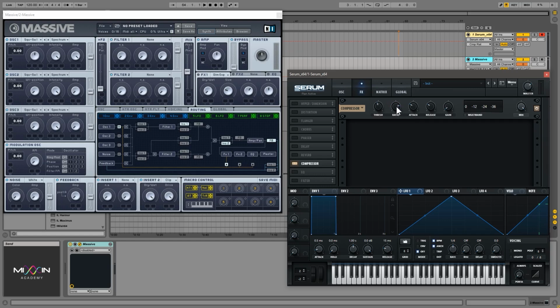So that part of the audio going over the threshold, being louder than this line that we set, is going to be 4 times less loud, or 5 times less loud, or 6, 7, 8, 10, maybe even limitlessly, so infinite to 1. That's what the ratio is. 2:1 means that the resulting signal going over the threshold is going to be twice as low in volume than what it originally is that goes over the threshold.